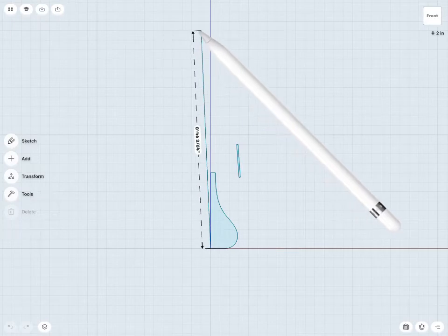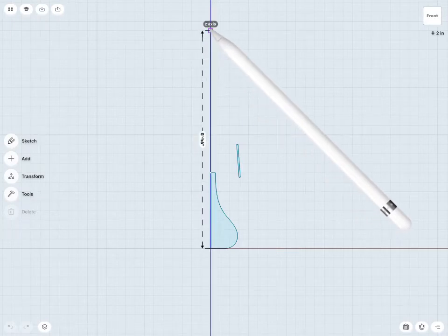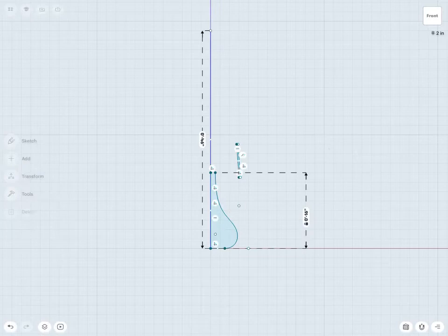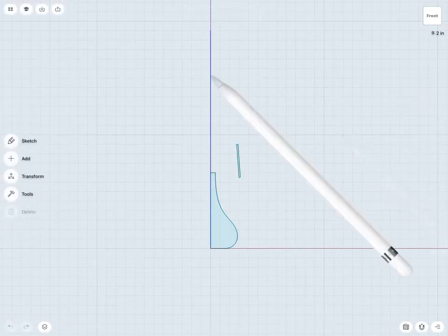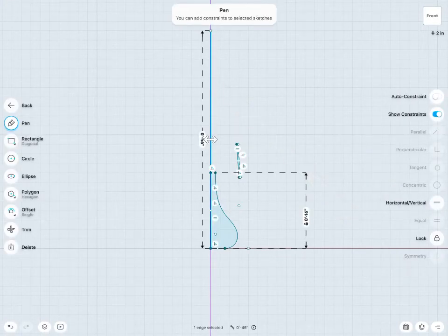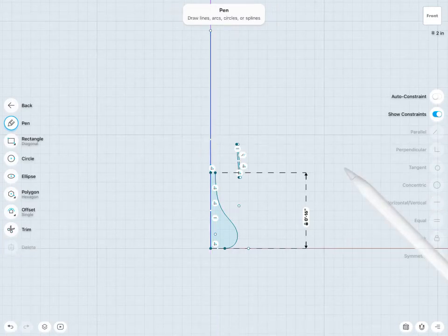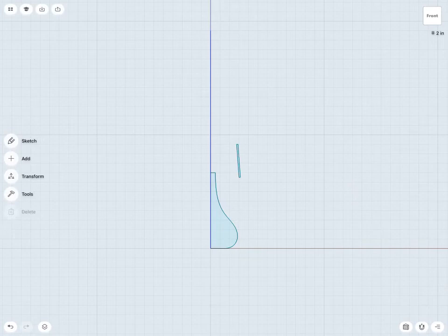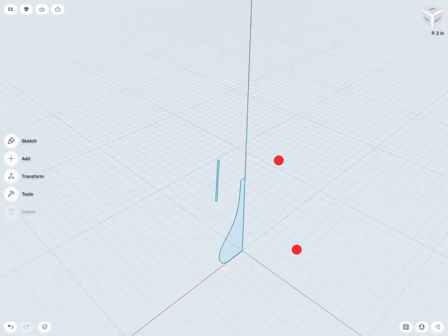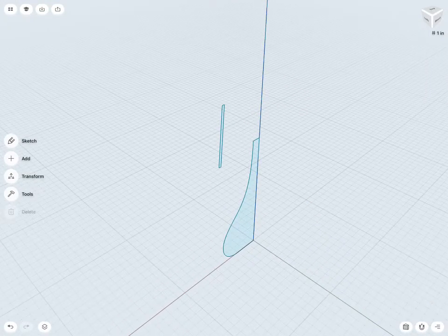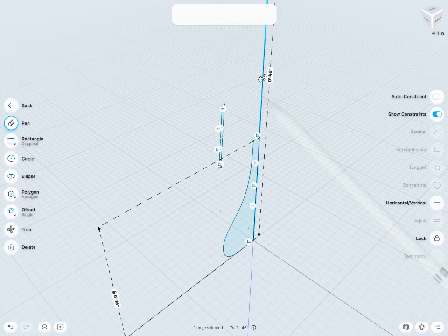I'm going to want to make sure it's exactly straight up this Z-axis here. So I'll throw in something like that. Now this line will be the line I'm using to revolve both of my sketches about. Now doing the revolve itself is a nice and simple process. I might jump into a 3D view again so we can see the revolve a little better. I still have this axis line available that I'll be revolving my sketches about.